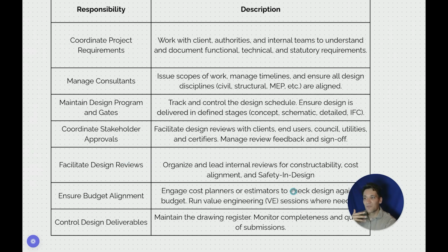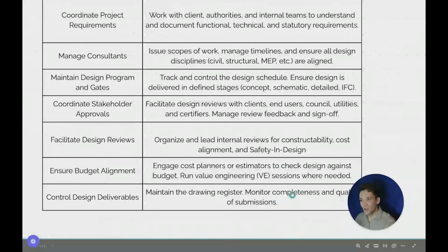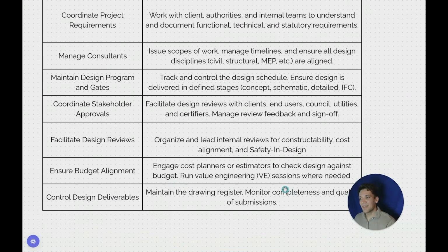On top of this, they're actually facilitating these design reviews. So they're organizing and leading the internal reviews for constructability, cost alignment, and safety and design. They're also ensuring budget alignment, so they're engaging with cost planners or estimators to check that the design is possible to build for the budget we've allowed for. They're also going to run value engineering sessions, so this is where they bring in the construction team, get them to review the design and look at cost-effective, cheaper alternatives.